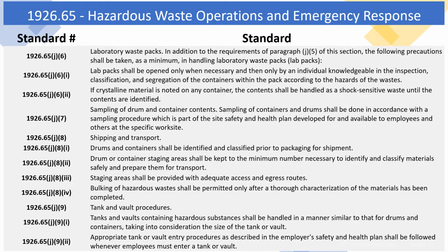1926.65 J6. Laboratory waste packs. In addition to the requirements of paragraph J5 of this section, the following precautions shall be taken, as a minimum, in handling laboratory waste packs, lab packs. 1926.65 J6 1. Lab packs shall be opened only when necessary and then only by an individual knowledgeable in the inspection, classification, and segregation of the containers within the pack according to the hazards of the wastes. 1926.65 J6 2. If crystalline material is noted on any container, the contents shall be handled as a shock-sensitive waste until the contents are identified.